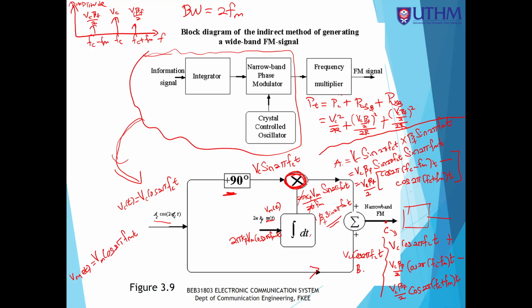Simple as that. So you need to know this in order to produce the output frequency equations. Given the input, find the output equations. From the output equations you can draw the frequency spectrum, find the bandwidth, and calculate the power. Does anybody want to ask a question about this? Do you understand? You want me to repeat or what?